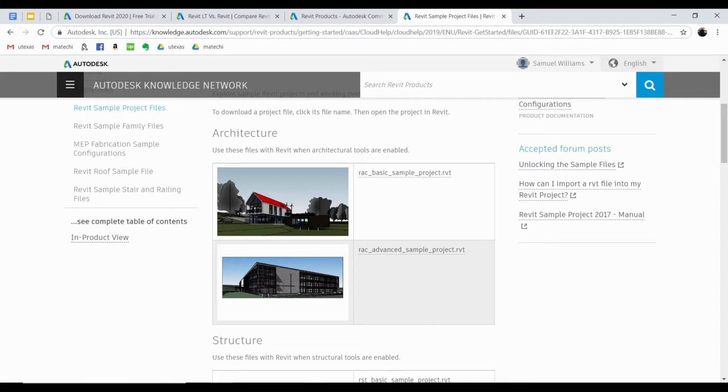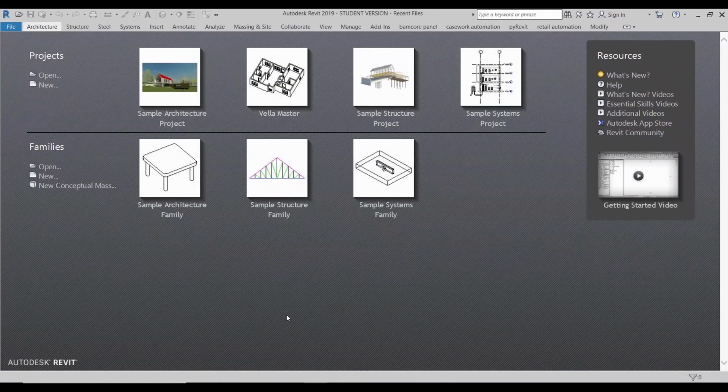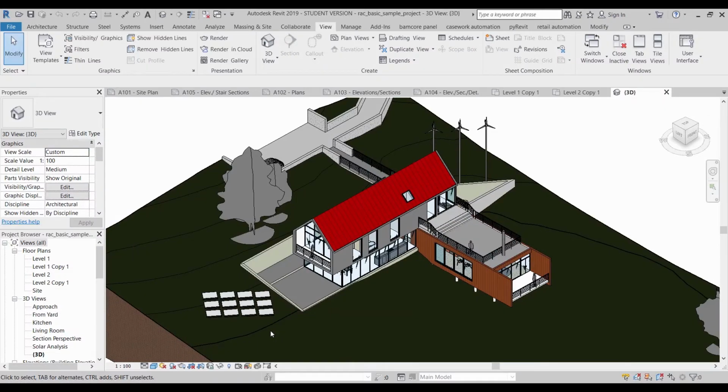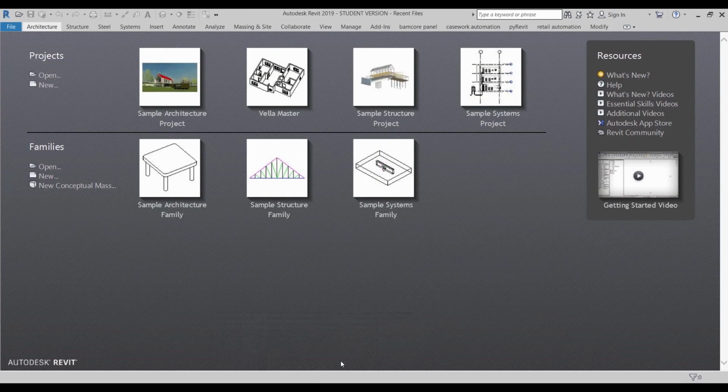file. So now that you have Revit open, we're going to create our own project. I have a reference project. Once you download this sample project, by the way, which we're going to recreate, I would actually launch a separate session of Revit, which you could just do by clicking it, and it'll do a completely different session of Revit and have it open for your use and for your reference. But for us, we're actually going to create a new project.